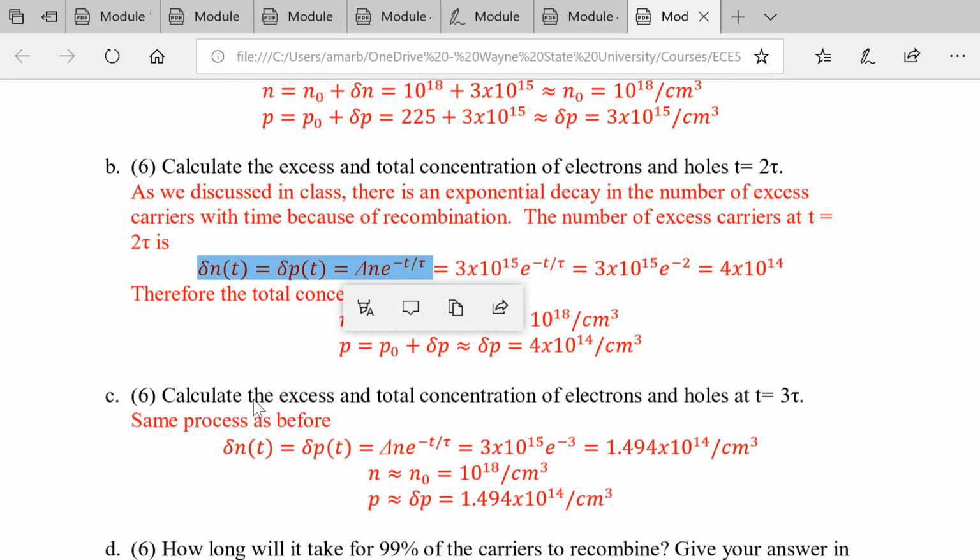Okay, and recombination, the 4th process. Yes. There were excess carriers generated, and those excess carriers recombine. Those excess carriers basically disappear over time. That's what's happening in this problem. When you turn off the light, the excess carriers die away. But it doesn't happen instantaneously. There's a certain decay time constant. Right? And that decay time constant is the carrier lifetime.